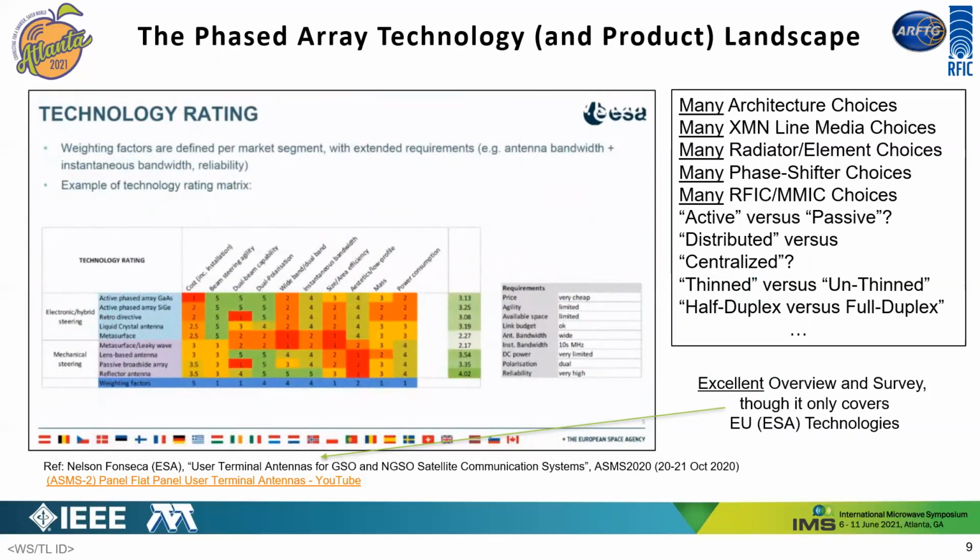Some phased arrays even downconvert directly at each element, while others employ digital beamforming techniques. Requisite phase shifter or beam steering functions can be pseudomechanical, metamaterial-based, or MMIC-based. Thinning is also sometimes employed in order to reduce the number of radiating elements, as a trade between lower cost and higher sidelobe levels.